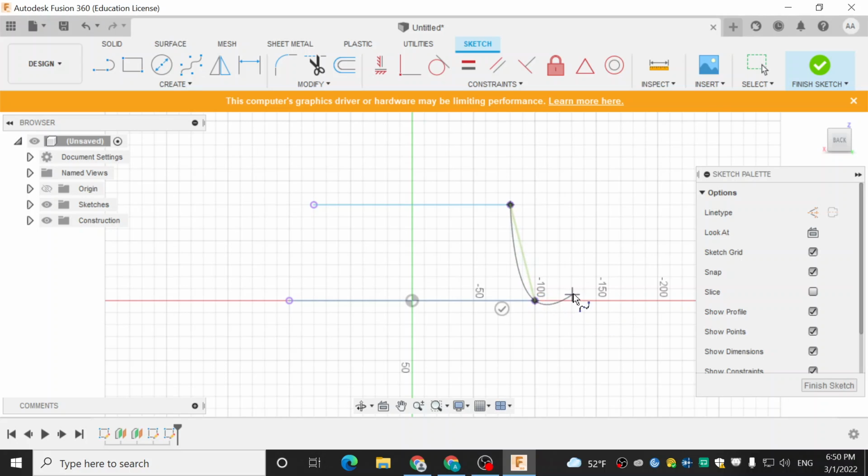Once you select that, you'll notice as you drag away, the line does not remain linear before you exit out of it. And that's because this isn't a regular line. This is a spline line. So you can use this to create free curves, basically. If we were to add a third point, it would change the curve of this line. But because we have only selected 2 points, it's going to give us the view of a straight line. So when you're satisfied that you've only selected 2 points and have a straight line, which currently for me will show green when I'm not hovering over it, I'll go to the top right and hit select.